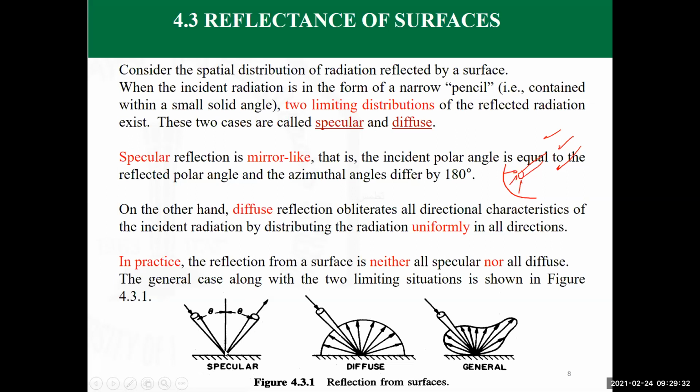The surface has to be shiny, has to be very smooth, has no corrugations at all, and which needs a little bit of machining, and it needs precise machining. Otherwise, what you will get is a diffuse surface like that. Energy will fall in, and then it will be reflected in all directions equally or homogeneously, and that's the diffuse surface.